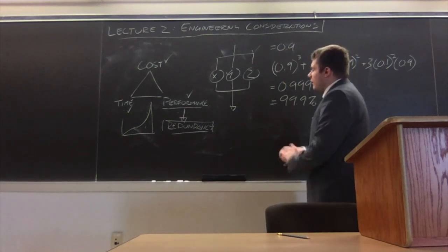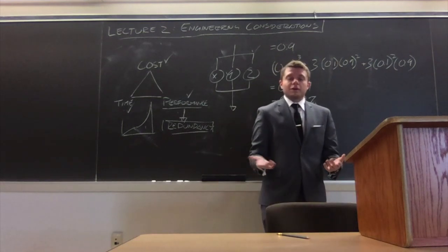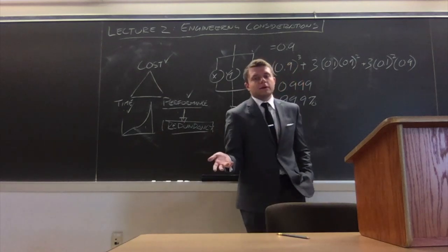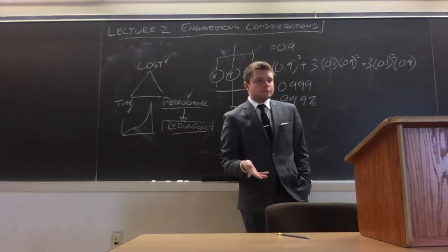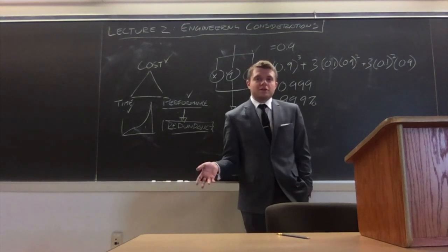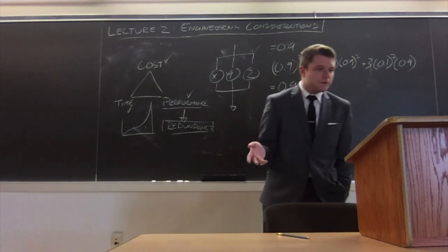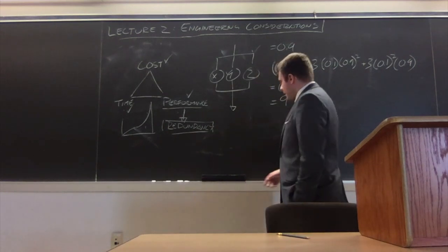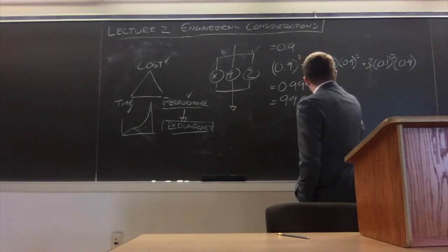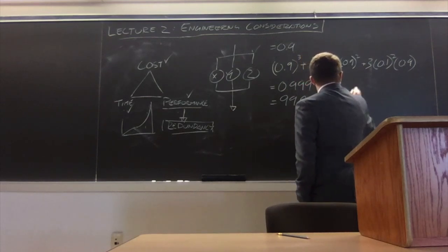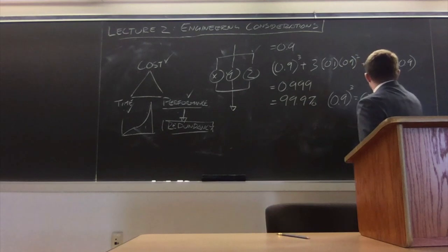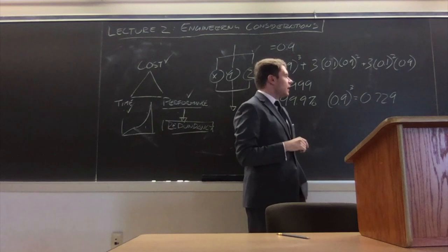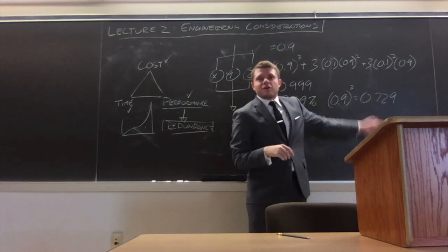So we think about this in one final application, which is what we talked about, parallel redundancy. What about serial redundancy? Well, one event has to rely on the next, has to rely on the next. And that's kind of what we talked a little bit about with staging. And a good example of this is, let's say, a 3-stage system where each stage is 90% reliable. For a 3-stage rocket with each stage that is 90% reliable, you have a 73% chance of a successful flight.